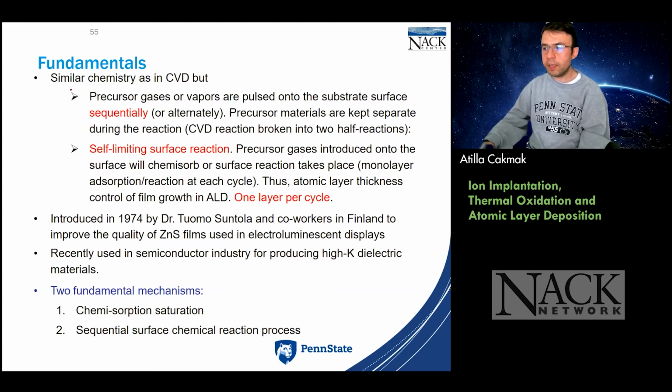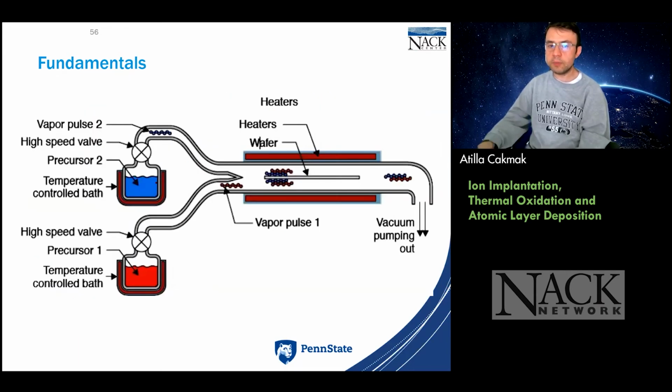I will talk about ALD, the atomic layer deposition. So it's similar to CVD. There's lots of text here, but I'm going to quickly go over the essential points. It's very similar to CVD, but different from CVD, we have precursors, precursor 1 and precursor 2. We'll introduce these two different types of gas into our furnace, okay? That's how we will grow this material in the atomic layer deposition fashion.